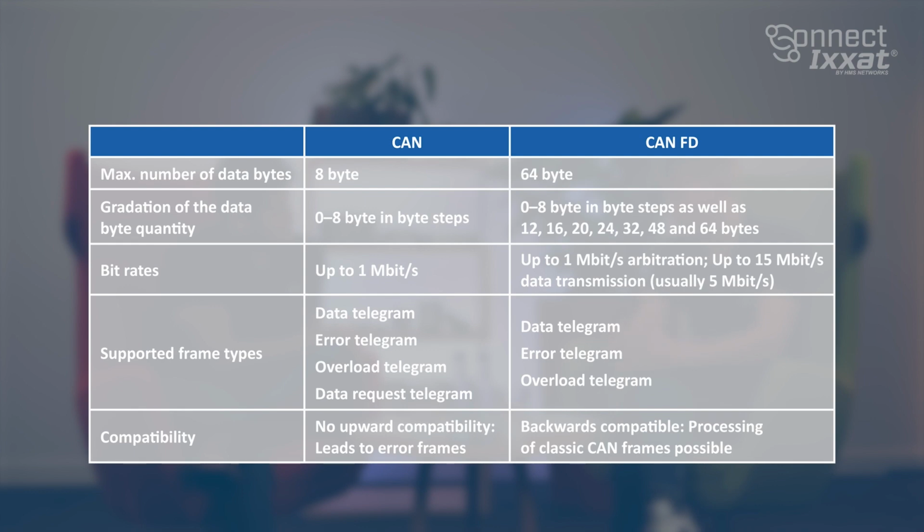A downside to CAN-FD is definitely the bus length. In practice we are experiencing a lot of trouble here. However, to be honest, this is really dependent on your specific topology. Another downside to CAN-FD, I think, is the cost. If we look at the cost for CAN-FD transceivers and CAN-FD controllers, we see that these components are more expensive than classic CAN components, and this obviously will lead to a higher cost in your network overall. But the developments in the last couple of years have been really promising that we will see an equal cost for CAN and CAN-FD networks.